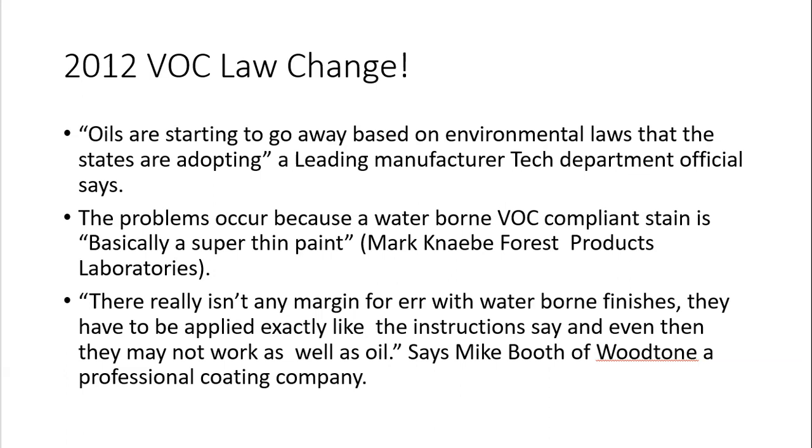And so I called Mark Naby again, because he's the world's foremost expert on wood finishes. And I said, what's up with this VOC law? And he's like, well, the problem with waterborne finishes is that because they don't penetrate, it's basically like a super thin paint. So you experience all the risks and trouble of paint, and you're talking about a much thinner coating, all right? And when I talked to a very known factory application expert about waterborne finishes, he tells me, well, there's just not a lot of room for error with the application. So you have to apply it exactly the way their instructions say, or it's going to be a problem.